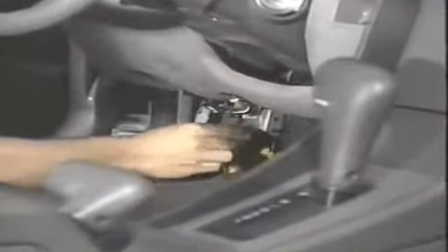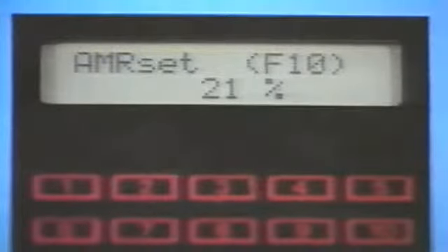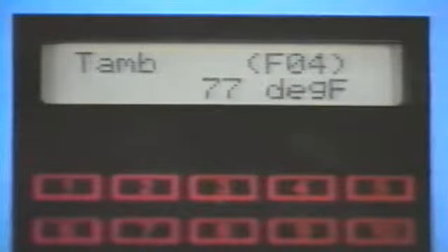The Select Monitor works in conjunction with the self-diagnostic system and provides detailed information about the system inputs, outputs, and component operation. With the correct cartridge inserted and the cable connected, any of 19 different function modes can be accessed. Functions such as actuator position, actuator command, compressor displacement output signal, or sensor values.